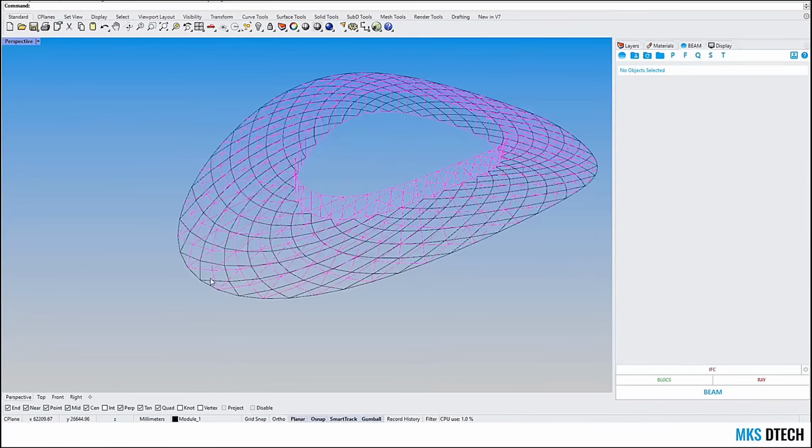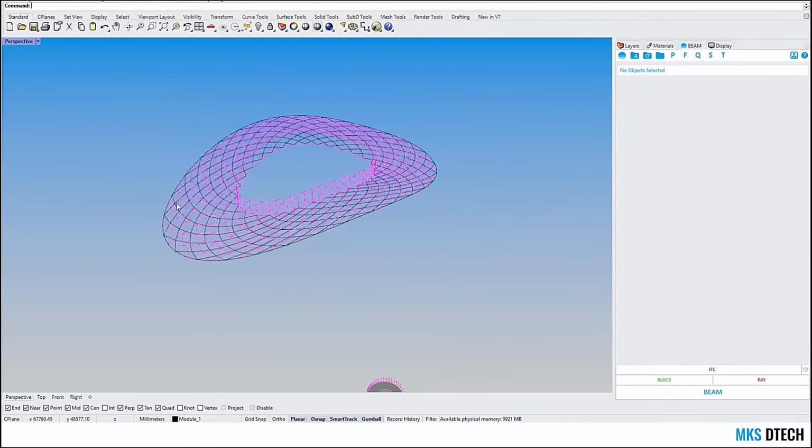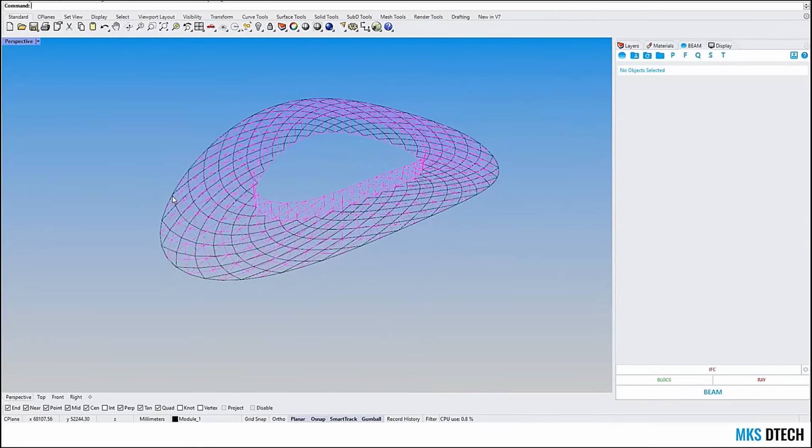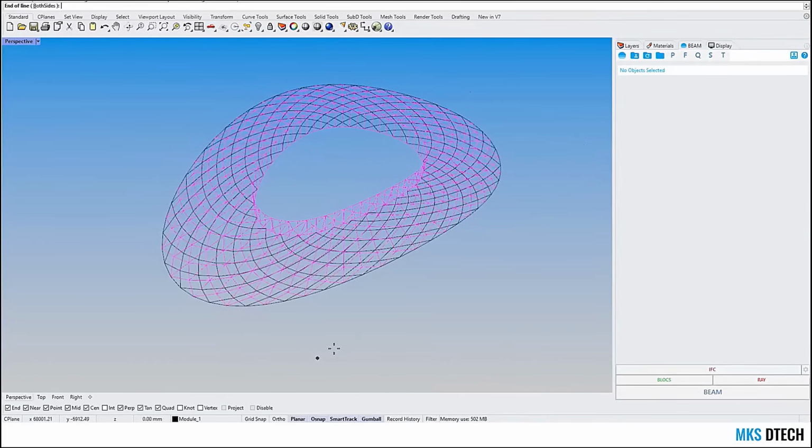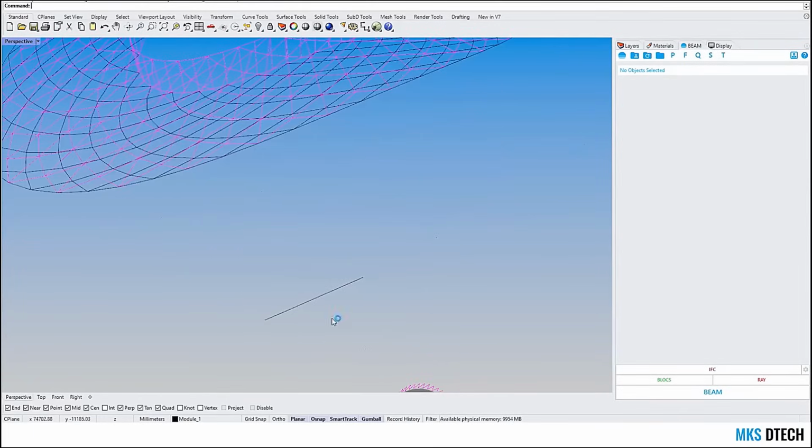Okay, at this point, we can start analyzing what's happening in this Rhino file, and we can start to assign properties to these lines and see how they are done. But first of all, these components in Revit are placed based on the number of vertices of these lines. So if we are talking about a 2-point adaptive, we're going to use a simple line. If we're using a 3-point adaptive, we're using a polyline with 3 vertices, or 4 vertices for a 4-point, and so on.